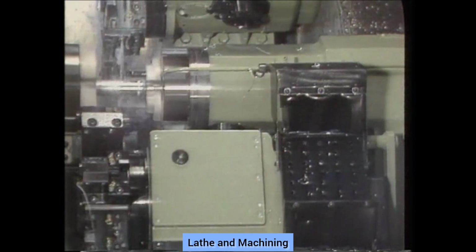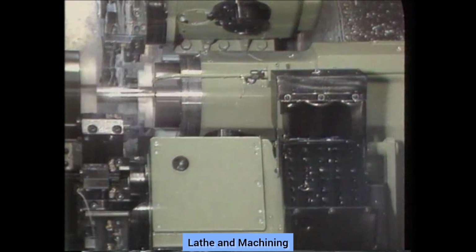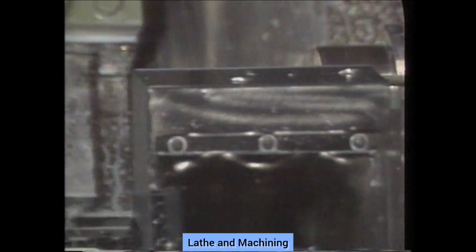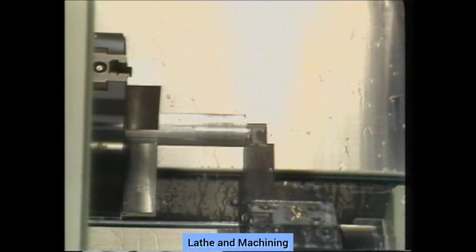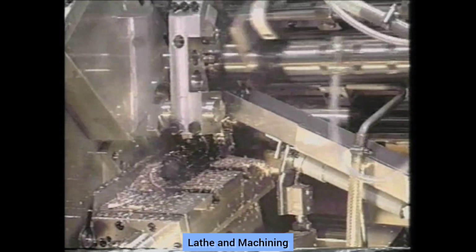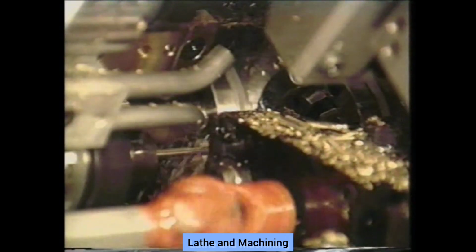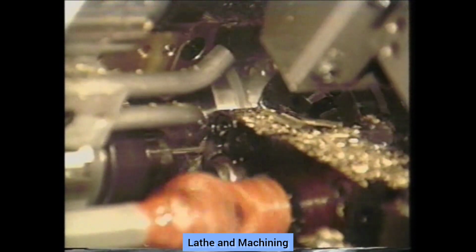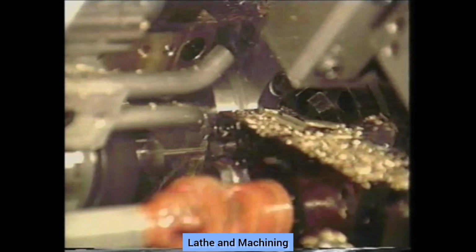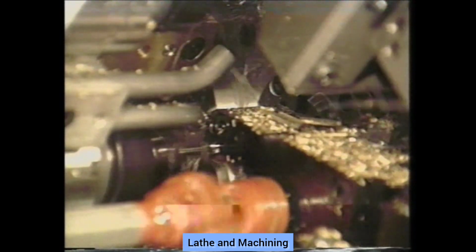The sub-spindle CNC lathe uses a secondary or sub-spindle to pick up the work from the main spindle. Another workpiece is then fed to the first spindle, running both spindles at the same time. Automatic screw machines are for high production turning and operate unattended. Cuts on the end of the work are combined with cuts from the side for rapid production. There are single spindle and multi-spindle types.